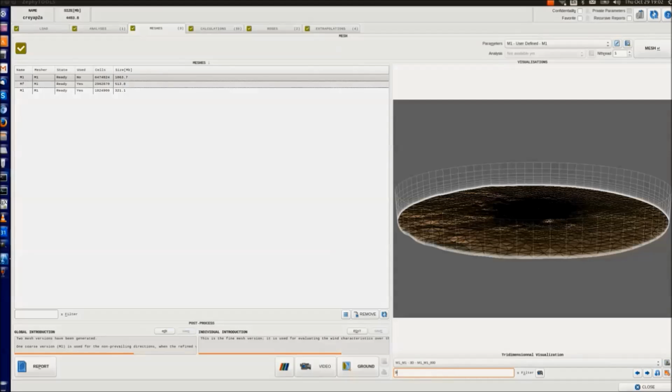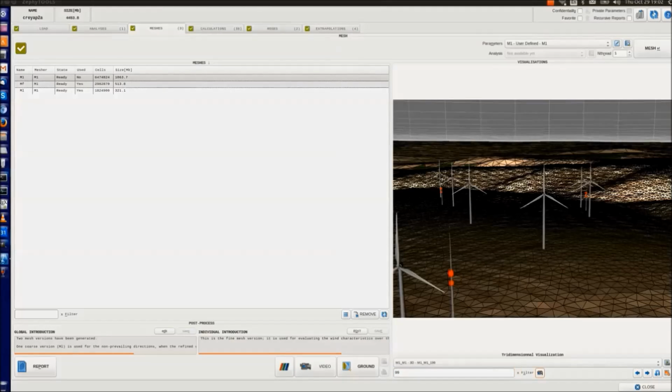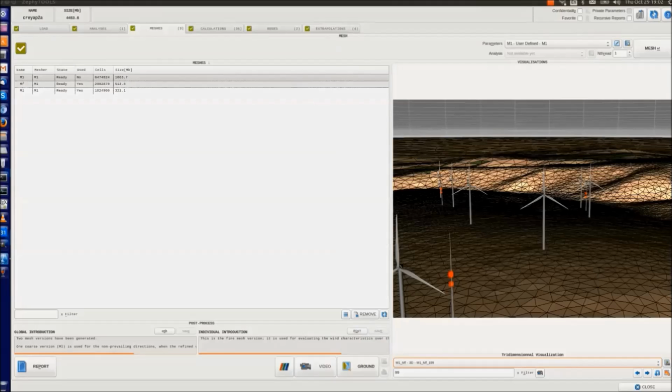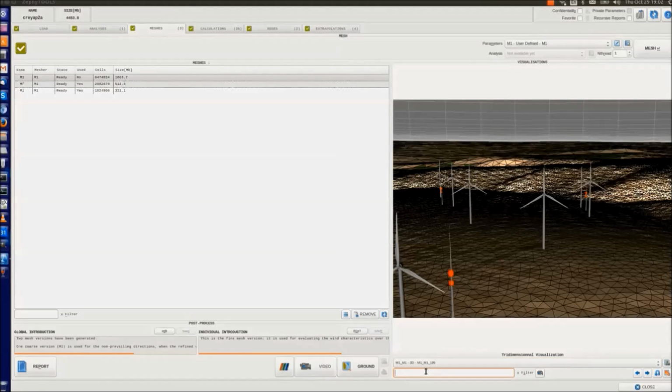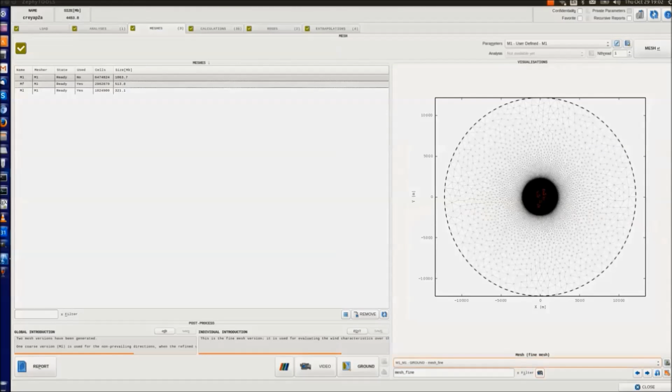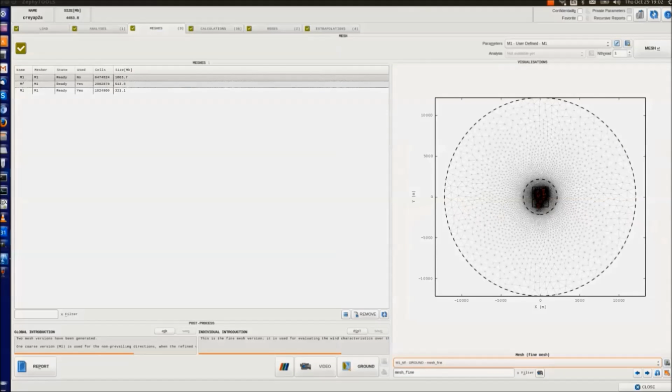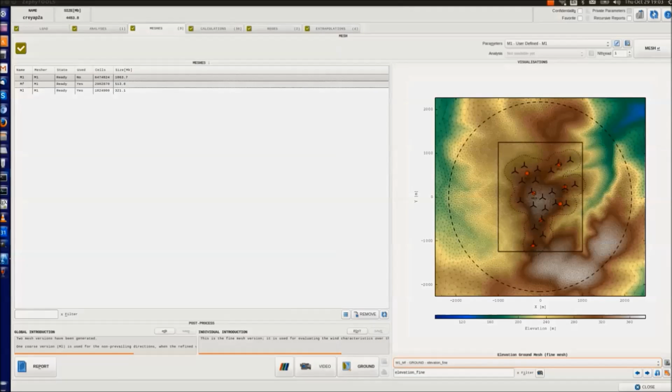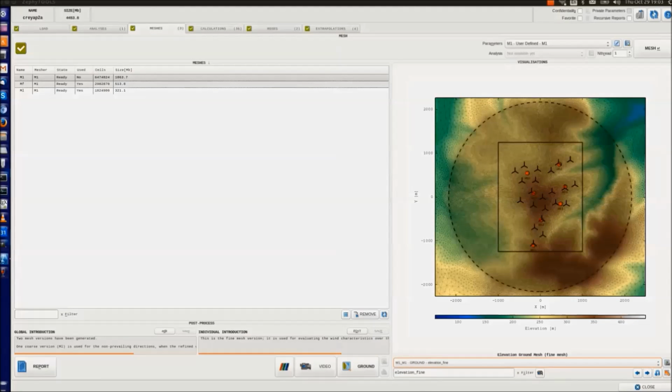So let's start with the meshing part. As you know, in ZephyCFD, we're using unstructured meshing techniques as well as a cylindrical calculation domain. Apart from the 6.5 million cells that were defined through ZephyCloud, we have also defined two other meshes, one with a bit less than 3 million cells and another one with 1.8 million cells, so that we can compare different levels of refinement.